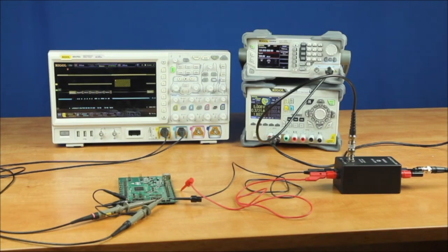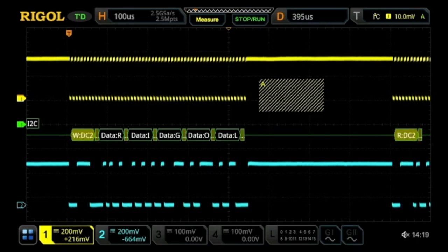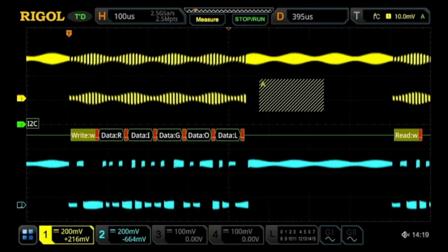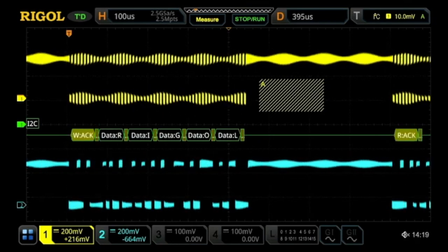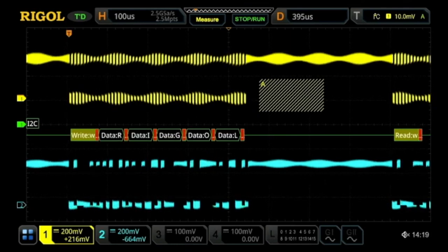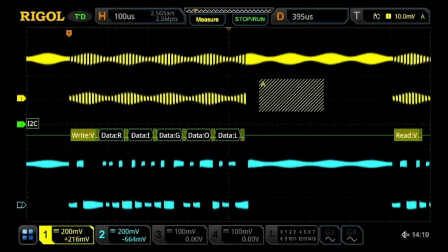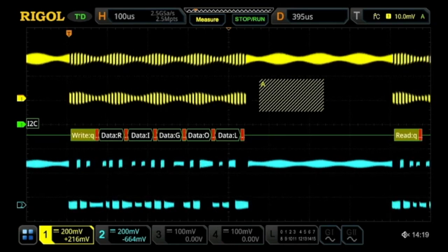Let's go ahead and look at the scope. Here, as we start to turn the power up, we start to see some effect of modulation on our signals there. Not as much as from the radiated high power emissions, but still seeing some changes that could affect operation. So this is a great validation check to see where you are in terms of conducted immunity testing.